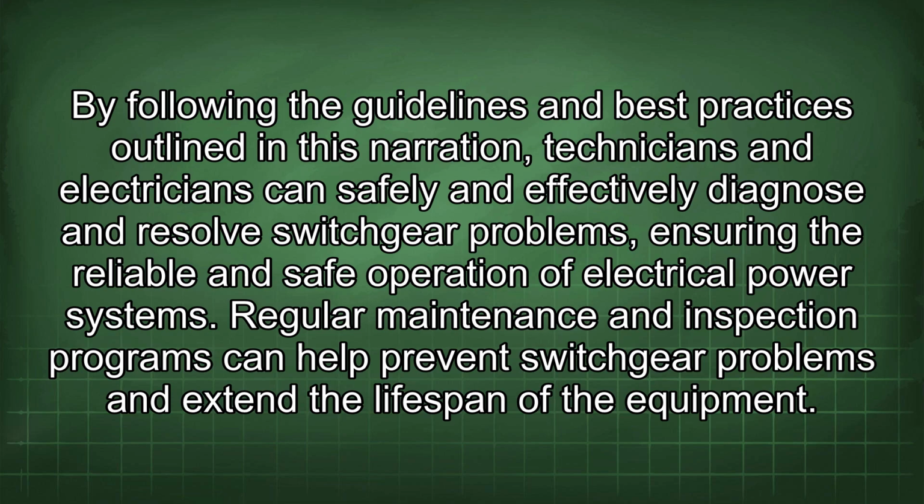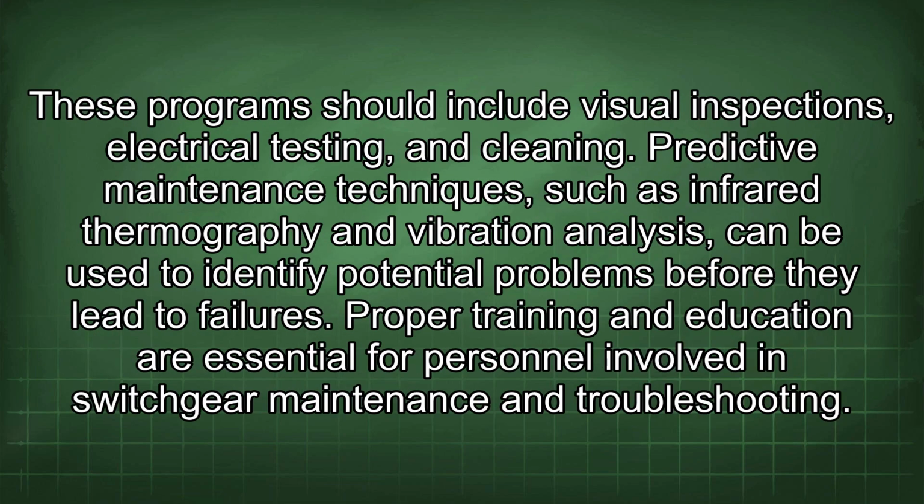Regular maintenance and inspection programs can help prevent switchgear problems and extend the lifespan of the equipment. These programs should include visual inspections, electrical testing, and cleaning. Predictive maintenance techniques, such as infrared thermography and vibration analysis, can be used to identify potential problems before they lead to failures. Proper training and education are essential for personnel involved in switchgear maintenance and troubleshooting.